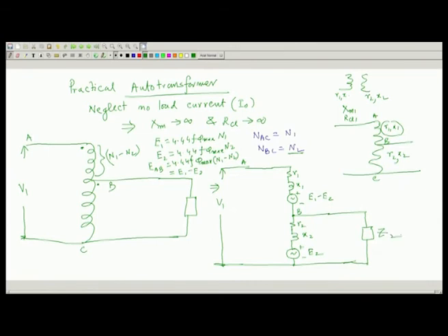So, immediately we see that it is not as simple as that of a 2 winding transformer, where the equivalent circuit was R 1 X 1 and so on, E 1 E 2. Here this is what it should look like, and there will be a distinction between V 1 and... see, if you start from this to this, in so far as induced voltage is concerned, it is fine, E 2 will cancel and E 1 induced voltage. But there is a mix up now.